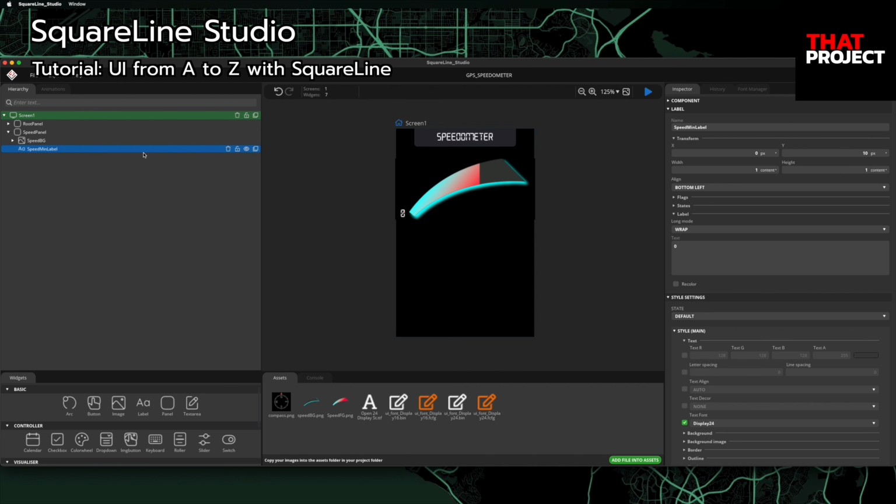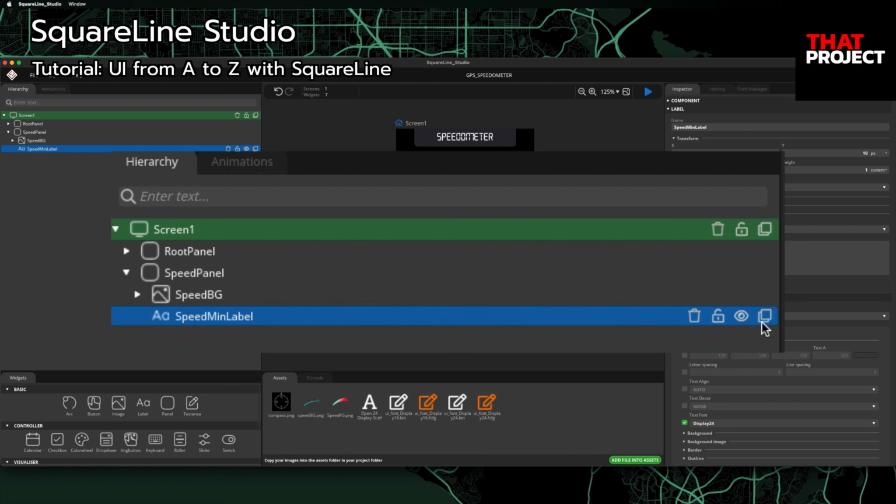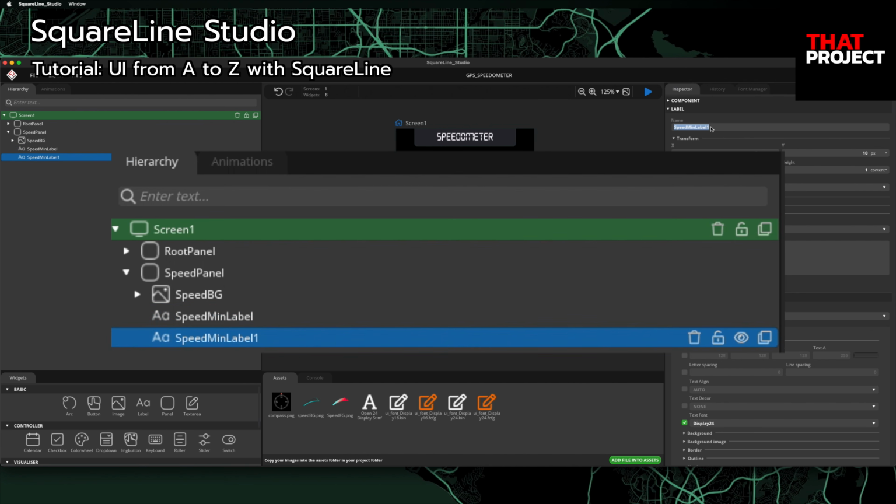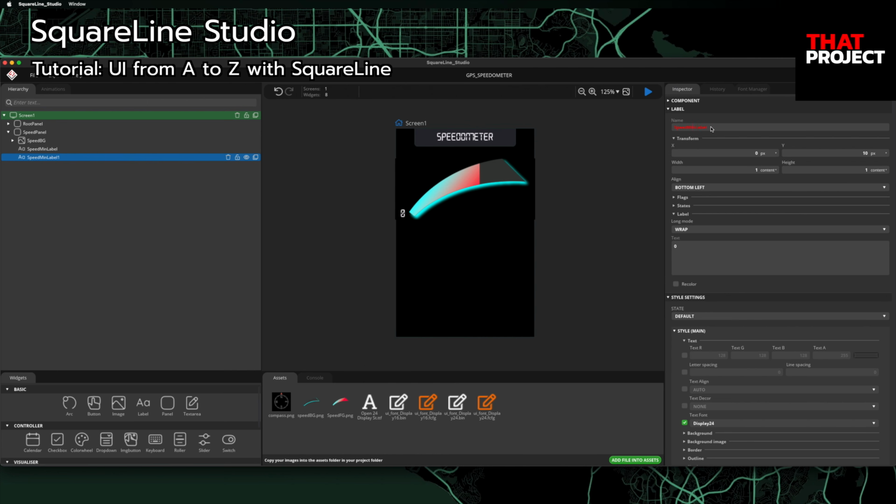In this case, we can duplicate widgets very simply. Click this duplicate icon to easily create one more identical widget. After that, you need to name it again. Note that all widgets must have unique names. The same names are not allowed. After changing the text to 100, change it to the top right alignment. I will change the Y value to move it further upward. This is enough.